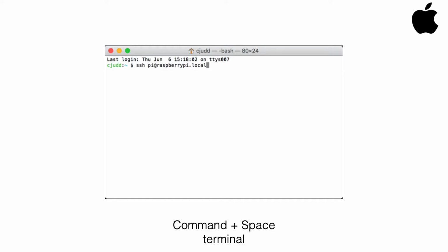What happens is the Raspberry Pi Zero W creates a special Bonjour network that allows you to connect to a named device. Its name is raspberrypi.local. On that device, there is a user configured named pi, so you're going to log in as that user. When you are prompted for a password, the password is raspberry, and that will get you in.